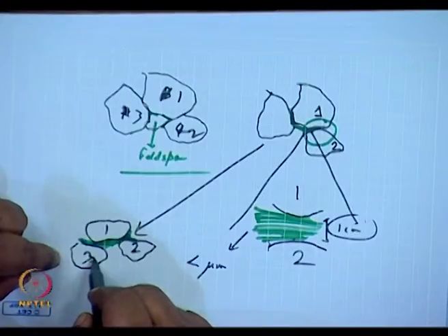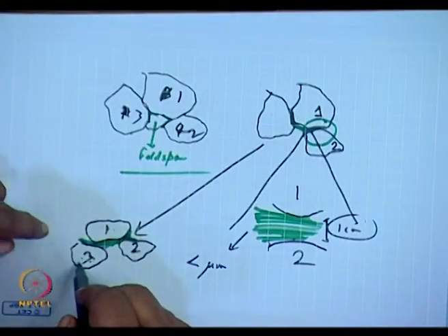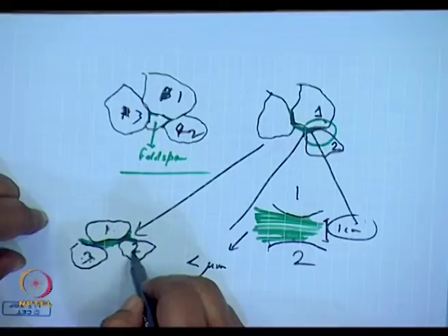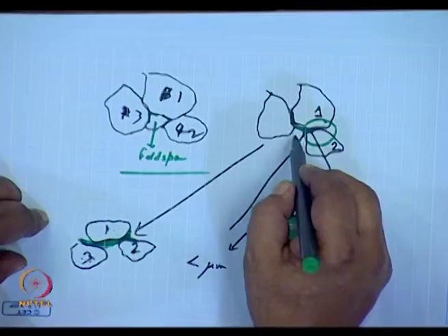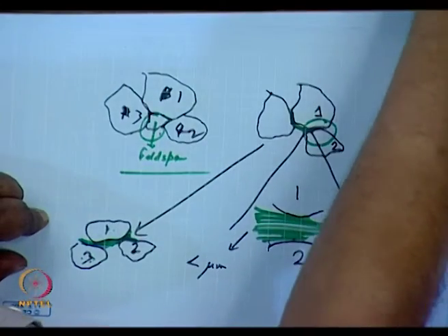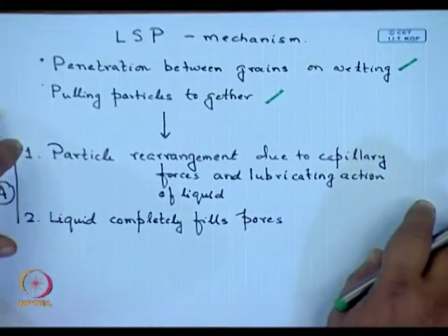And as I showed over here, each of these silica and clay grains is getting smaller and smaller, because the liquid is forming as the original feldspathic melt reacts. What does this allow? Because the liquid has wet the surfaces, it is pulling the particles together, but before that, as I have just said, it is also dissolving the solid. Which part of the solid?